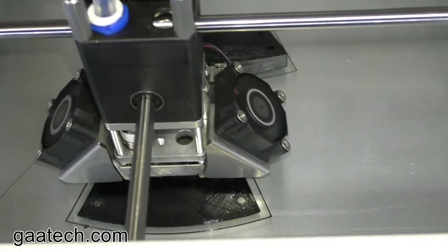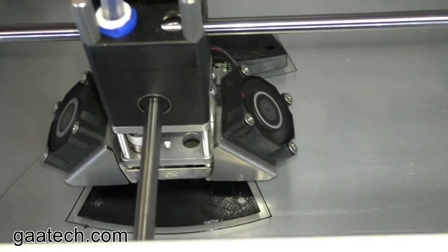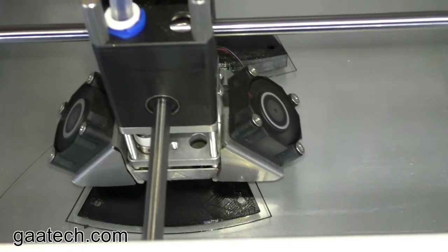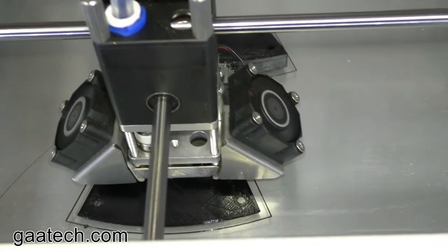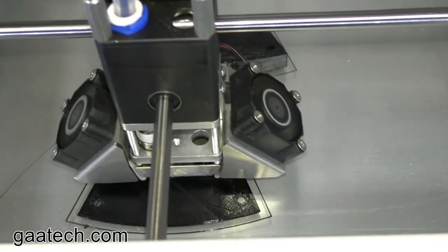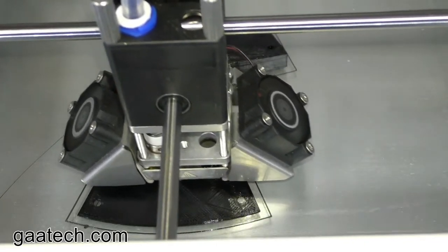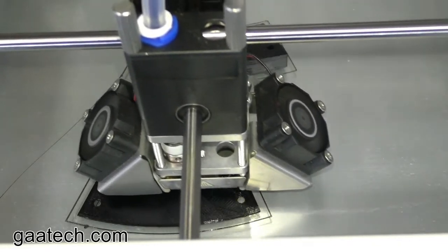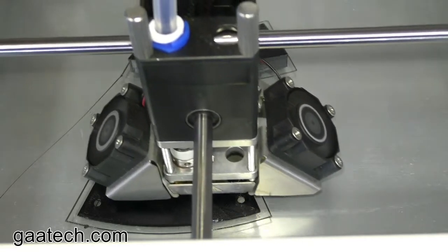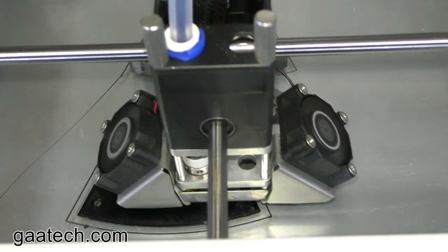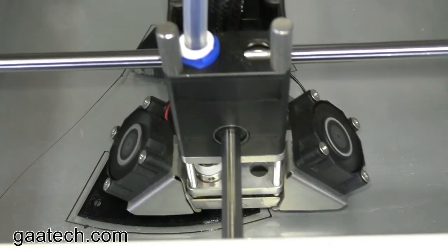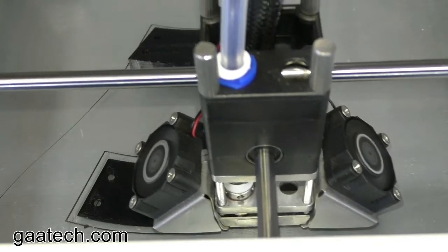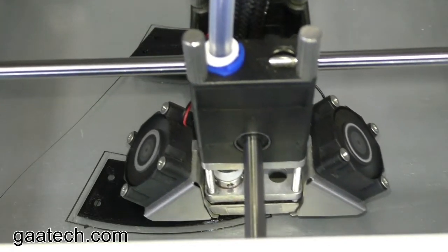So this part here, you can just see here where my finger is, this is my Bowden tube where the filament is being pushed through this tube. My filament drive mechanism is at the back of my printer, so the spool of filament is tucked away at the back. It's just held on by a spool holder, really, I should call it. So then the filament's pulled off the spool into the drive mechanism, and then it's pushed up through the Bowden tube and then into the hot end where it's melted and extruded.